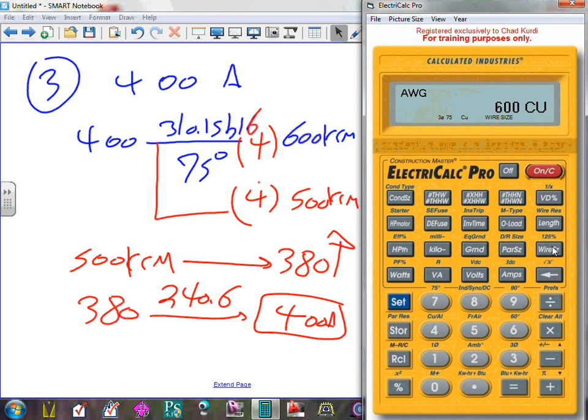So you talk about 100 amp or higher. When you come to 100 amp or higher in 3-phase 480/277 or 208/120, the neutral is really in reality carrying only the difference between all these, and for all practical purposes, code wise, it will count as 0 in terms of current. So you're really looking at 3 conductors. Yes. Feeders.